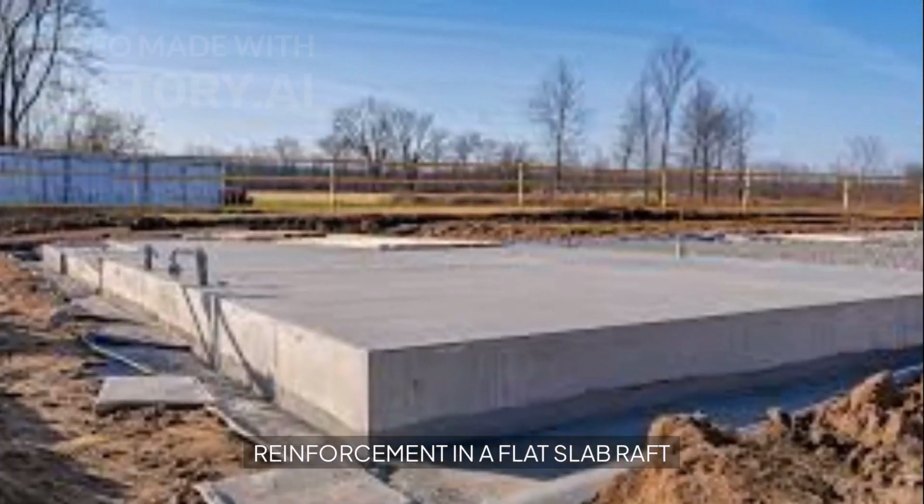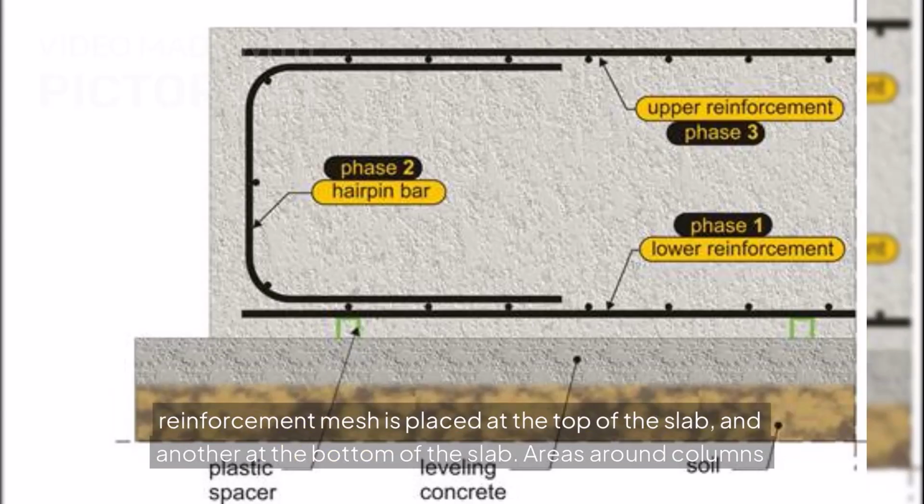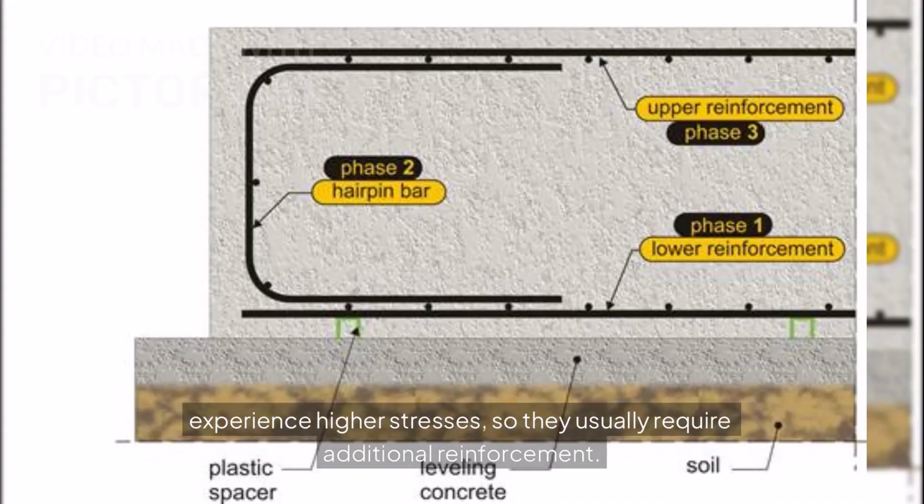Reinforcement in a flat slab raft. To resist bending caused by soil pressure and column loads, reinforcement is provided in two layers. One reinforcement mesh is placed at the top of the slab, and another at the bottom of the slab. Areas around columns experience higher stresses, so they usually require additional reinforcement.